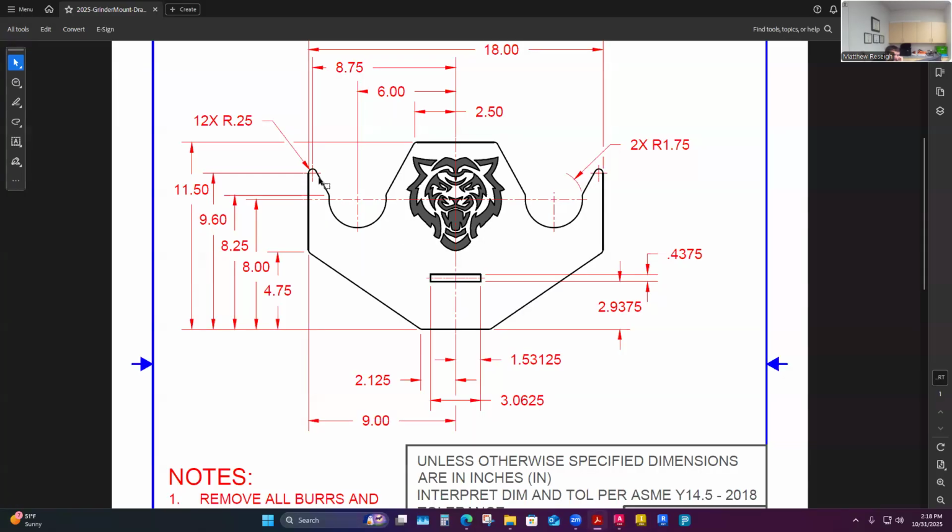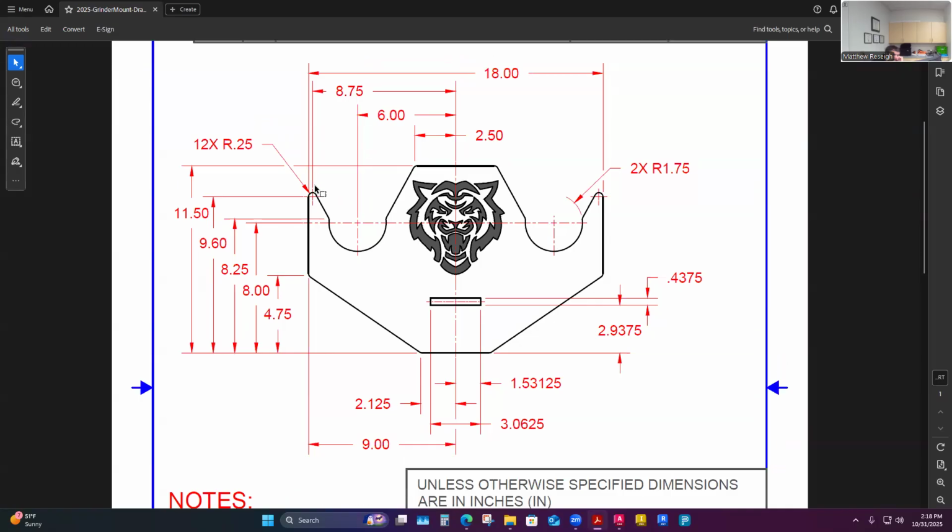I'm here, but I don't know where the line and the circle touch, to where they come down and hit this circle. So I feel like I'm going to put in this circle. That's going to help me for one. So I'm going to look at the circle center lines and mark those with construction lines. It comes up 8 from the bottom to the center of that circle. And then where that line and that circle intersect is actually above center. So this is technically more than half a circle to support the grinder.